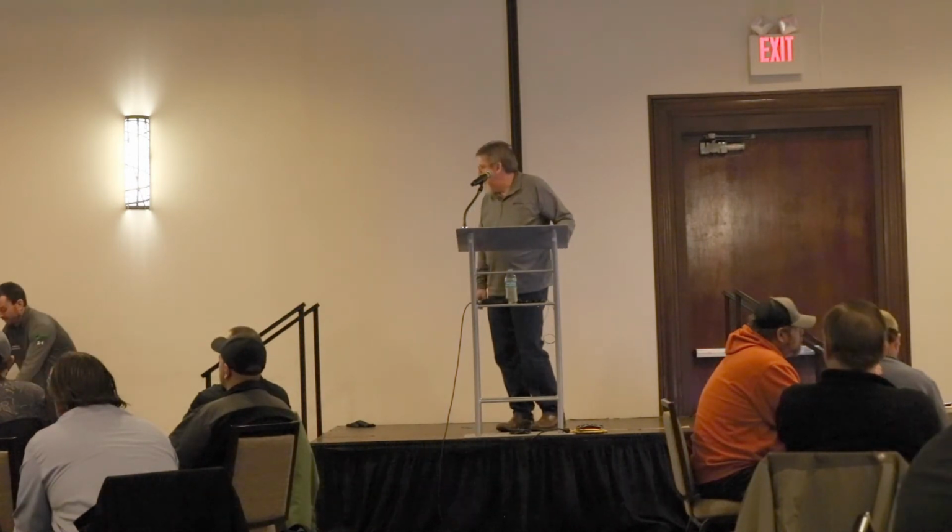Like Brad said, in your QC plan you have to talk about the process balance and how you're going to figure out how to keep everything in balance: plant production, transportation, how many trucks you need, your paver speed, and how many rollers you need to accomplish your goal for the day.